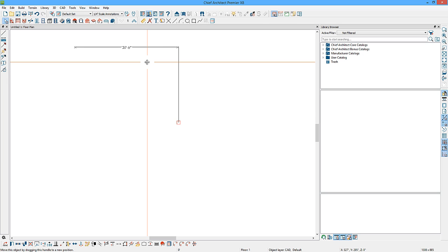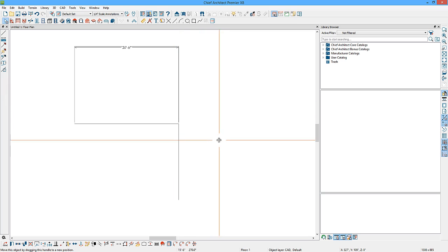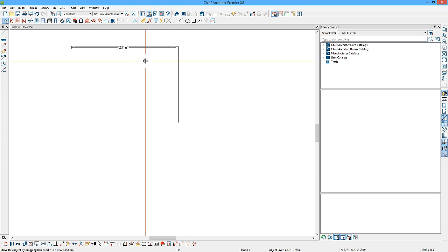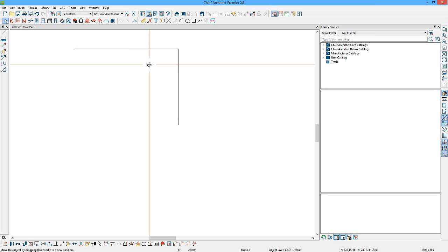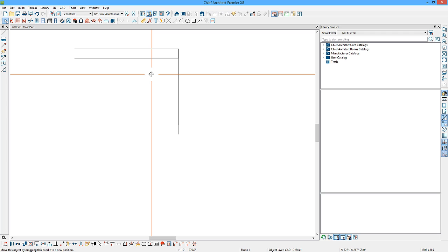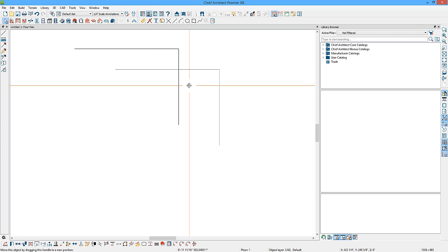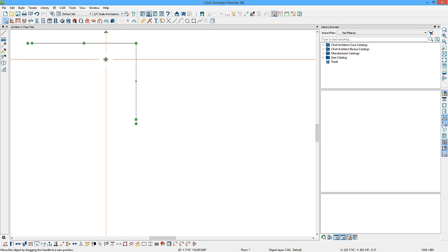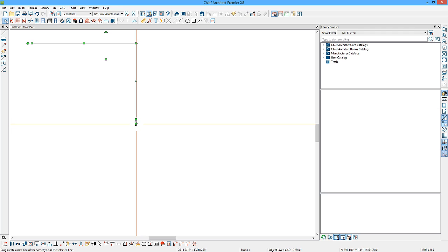These are the two directions allowed by angle snaps. If I try to move it in a 45-degree angle, it won't allow it, unless, as I click and drag, I'll hold down my Control key. The Control key will allow it to move freely. On a Mac computer, this will be your Command key.